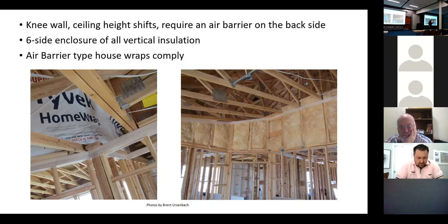Yep. Now I have seen, and in fact, I'm really toying with doing it on my big garage I'm going to build, Atlas Roofing, who manufactures polyiso material, they have a system, and others are just putting it together, that you put the foam on top of the roof deck, however many layers that you want. You screw down sleepers, you create a 1.5 inch ventilated space on top of your foam, ridge vent and soffit vent.